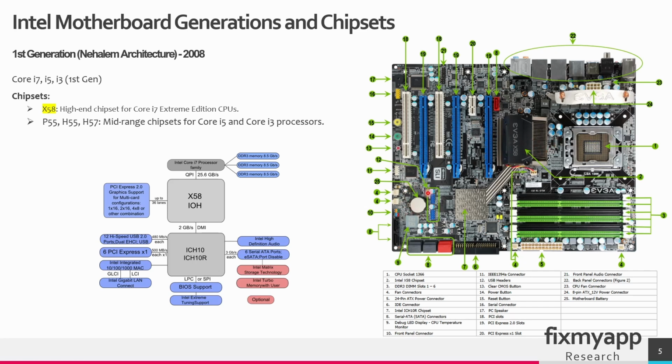This is the RTC circuit. This is the 24-pin ATX power connector. This is the CPU power. It is a Super I/O chip. So this handles the data signals from the buttons, the reset buttons, the keyboard signals. So also the low speed signals, it will go to the South Bridge. From the South Bridge, it will go to the CPU or the North Bridge.